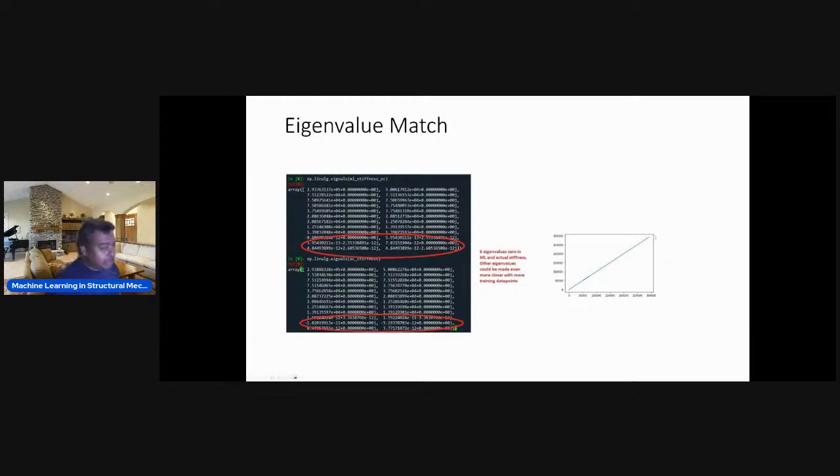And so it becomes very clear that for cases where you are not trying to solve a finite element problem, but, for example, a materials problem where your constitutive formulation is of higher importance compared to the element formulation, for those cases, with a very close accuracy between the finite element stiffness matrix and the machine learning stiffness matrix, there is always a choice or decision one can make, playing with either the machine learning component of the stiffness matrix or the finite element component of the stiffness matrix.